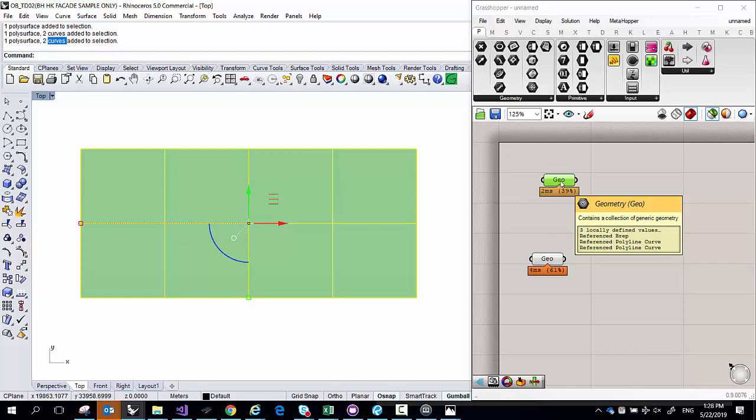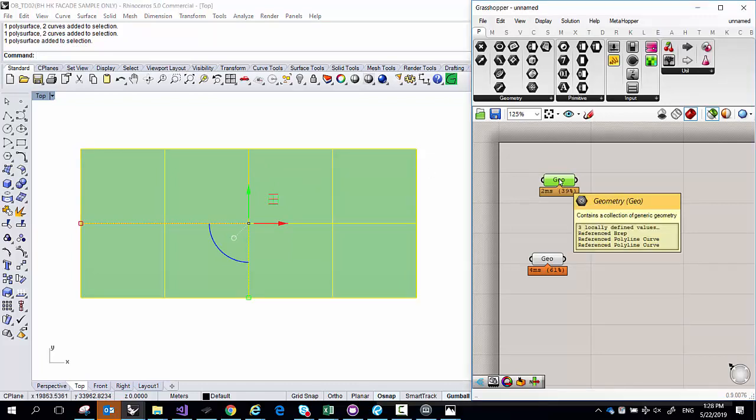It's a boundary representation, which is effectively a surface or a poly surface. So you see what I mean? If we just focus in on saying surface, the word surface doesn't really mean anything if we're talking about computational engineering, because there's the first principles engineering definition of a surface, then there's the definition of a surface in Rhino, then there's the definition of poly surface, and then in Grasshopper, both the definition of a surface and a poly surface are in one other word, which you guys don't know, an English word, a B-rep, which actually stands for boundary representation.